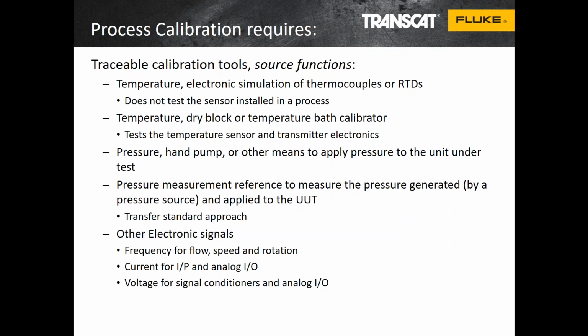Other electronic signals, if we're doing flow or speed and rotation, being able to source frequency, sourcing current for testing I to Ps, and the inputs and outputs of control systems, and of course voltage for signal conditioners and analog I/O that have 1 to 5 or 0 to 10 volts inputs.